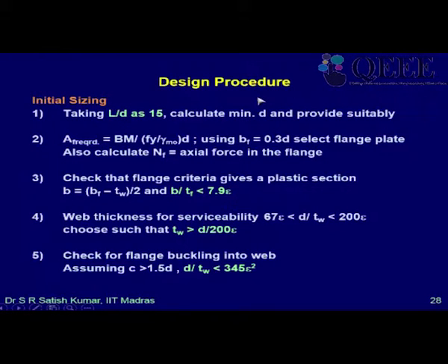Now just to summarize the design procedure: initial sizing of the plate. Like yesterday I told you that any beam design has to pass the serviceability limit. To ensure that it will pass the serviceability limit, you should keep the depth such that L by d is between 12 to 20. We will keep it around, let's say, 15, and calculate the minimum d.